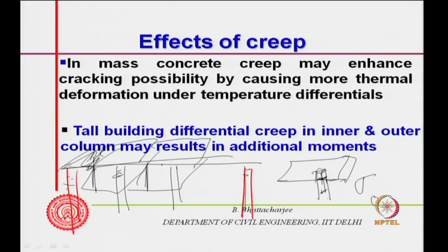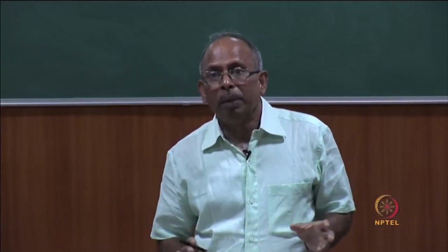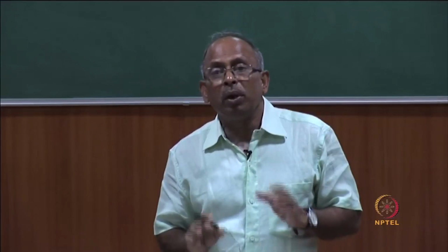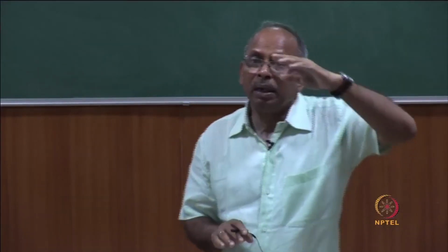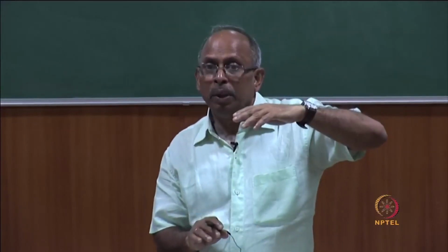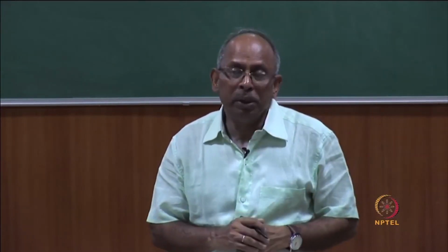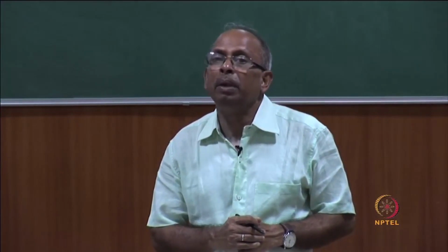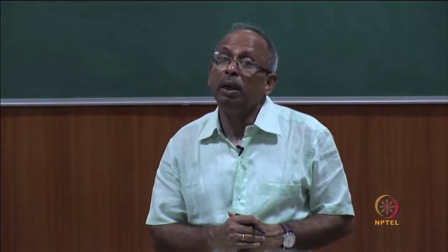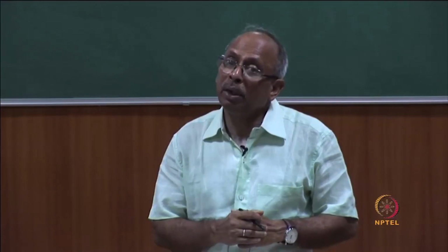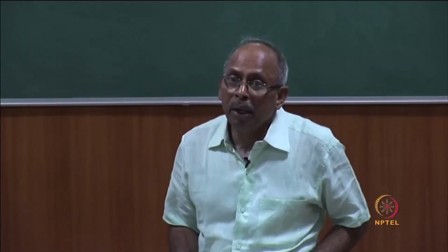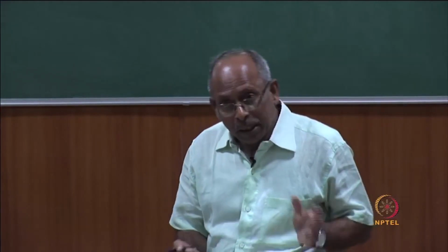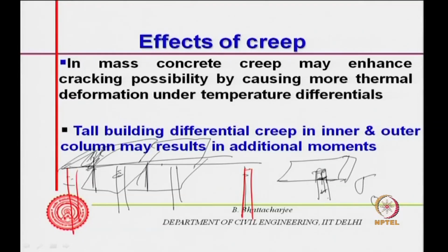Now, what is the result? If it is a short structure, not a very tall structure, it may not have any effect, but if it is a very tall structure, where the column length is very, very high, this might result in overall shortening of the column, which may be appreciable. This effect is not seen in relatively shorter buildings, only in tall buildings, say 30, 40 story buildings and so on. If one calculates the difference in creep deformation over the long run between the internal column and the external column, there may be some differences.